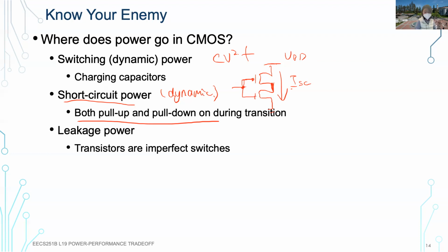So Hyun-suk is right, the leakage power is still very important. Again, different people have different rules of thumb. These days, people typically think about 2/3 of the power is dynamic power, and 1/3 is leakage power. Again, this is a rule of thumb. We'll see designs where a lot of power is spent on leakage power. We'll talk more about the trade-off, especially scaling voltage. So there is also a trade-off between performance and energy, and also between dynamic and leakage.